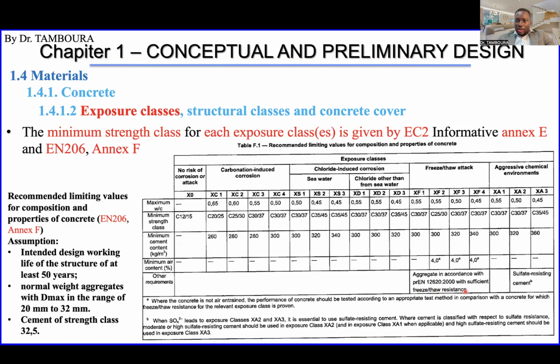Okay. And for the case of protection against chemical attack, in this XA2 and 3, you should have sulfate resisting cement.